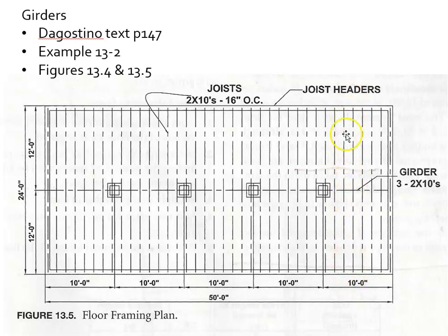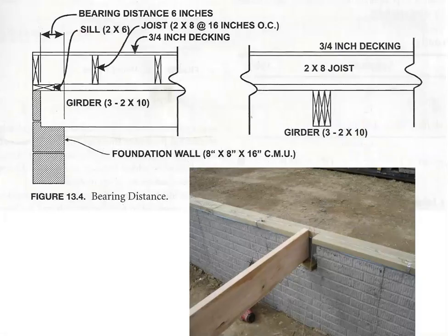So we can't see all the joist ends, but we're running parallel to the joist. So when we run parallel to a joist, we just see the face of it. When we cut a section perpendicular to the joists, we see the joists with the X's. That means we've cut through it. So if we cut through right here, we would see that X right there.